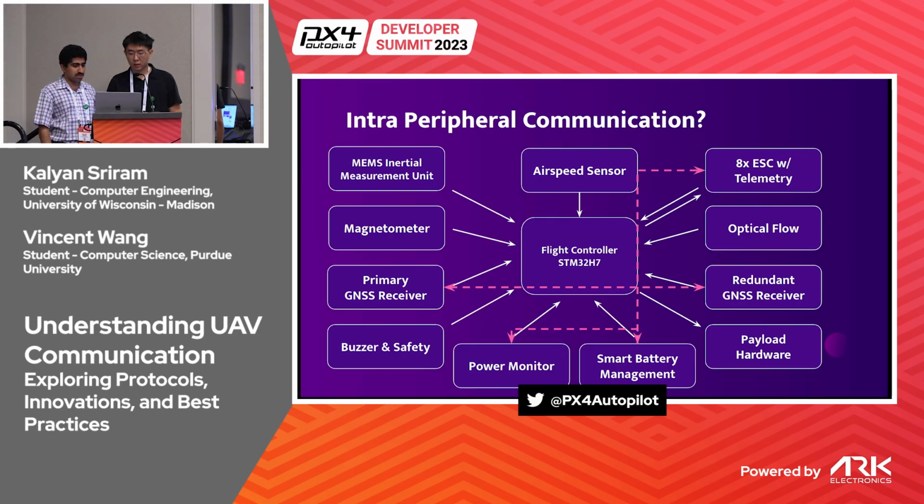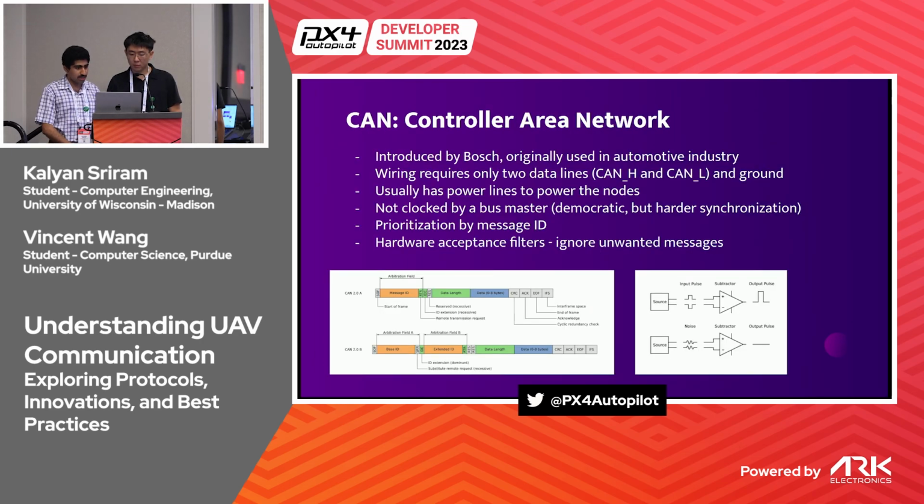And any device on the bus should be able to communicate with any other device. We also need a lot higher bandwidth than I2C or PWM encoding would provide. Enter CAN. The Controller Area Network is a hardware transport originally designed by Bosch for use in the automotive industry. Today, it is one of the primary ways the various ECUs, or electronic control units, in your car communicate. For example, your steering wheel might send information to your power steering unit.